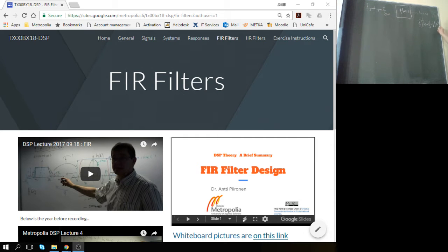Okay, today's topic is looking closer at the finite impulse response systems and how we can do filters based on this finite impulse response. The nice part of the FIR filters is that you can actually also make nonlinear phase response, but it's quite easy to do a linear phase response with FIR systems.